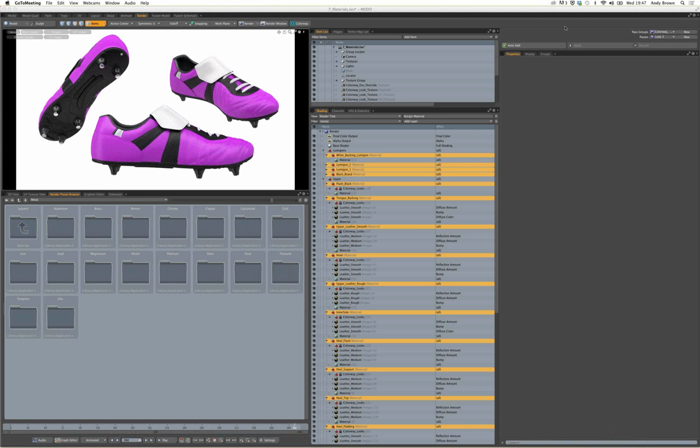Cool. Next question. Will changing the rigging settings change the model? In that example, yes. Because that canvas that I had inside that rig was all rigged up with deformers. So if I was changing those values, that basic shape was changing. So if I painted on that volume, because it had been UV'd, as I changed those values in the rig, the actual shape would have changed, and the sketch would move with that object as well.